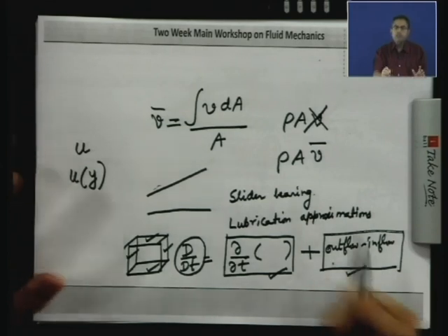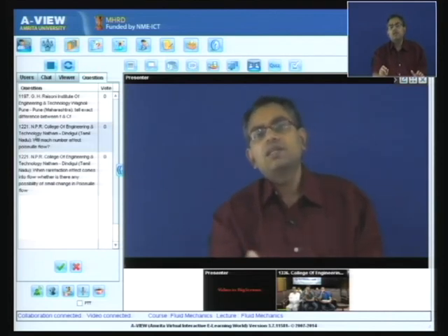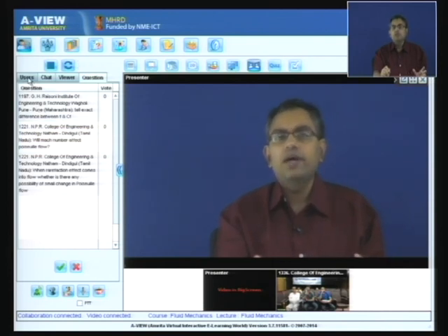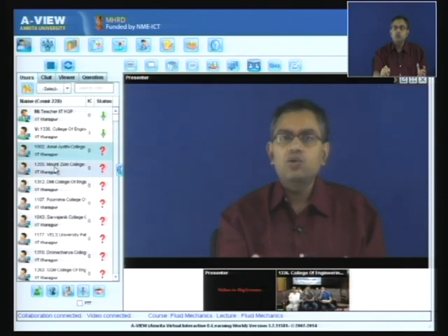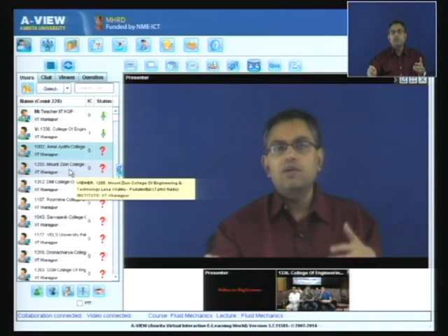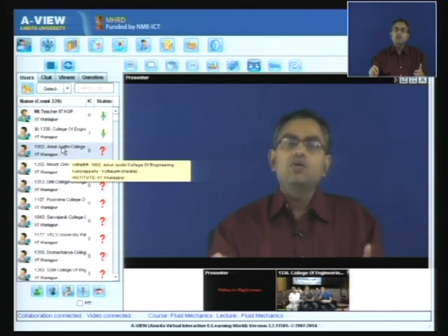So what we have written is the same as what we would have otherwise written with an arbitrary control volume using the Reynolds transport theorem, but we have written that in a more informal way which looks like the well known school level description of Newton's second law. This is just for the convenience of the beginners who are not so familiar with the Reynolds transport theorem, but they know how to apply Newton's second law for a system.